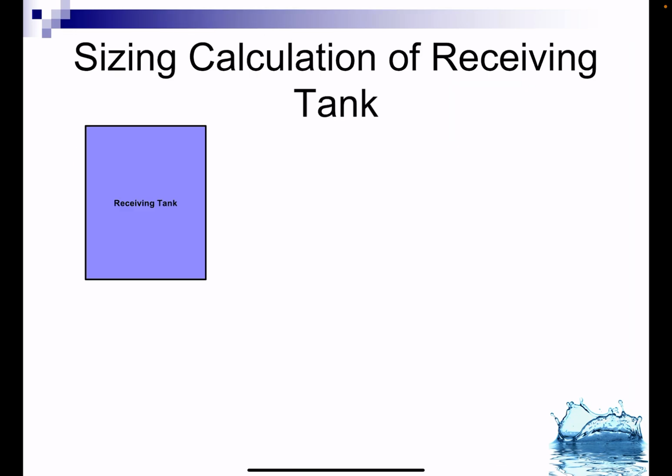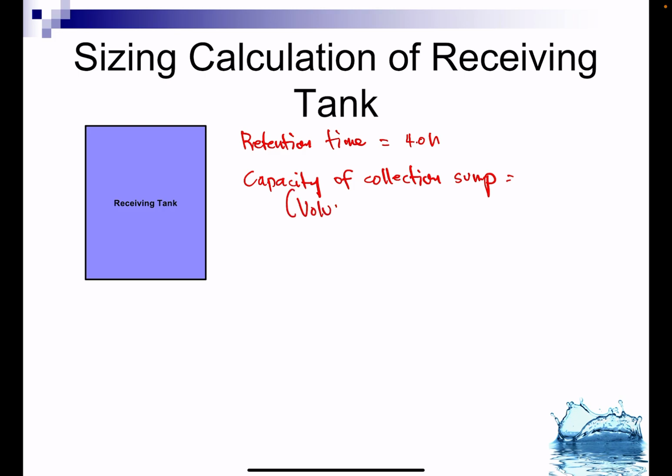Okay. So let's go to the sizing of the receiving tank. From here, you have to have an assumption of your retention time, how much time you would want your sewage to be staying in your receiving tank. Because from that, you will get to know the capacity of your receiving tank or collection. Sometimes it's actually termed as collection sump. So from here, assuming, lagay ka, say, 3 or 4 hours, your capacity of the collection sump is, this actually is your volume of your receiving tank.